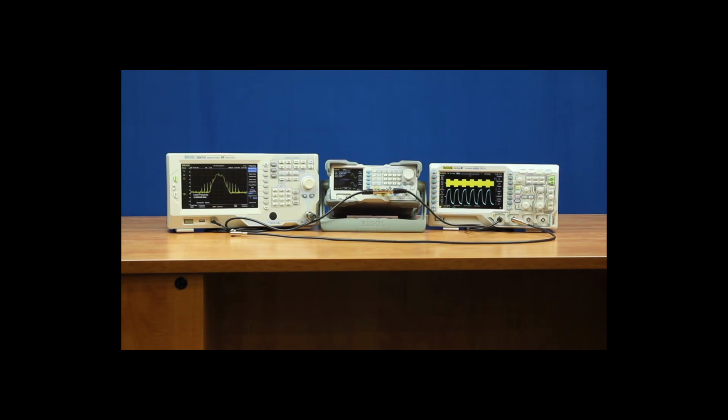So in the last example, we were transmitting and demodulating analog data. Here, let's look at a similar modulation, but with digital data. So this is an amplitude shift key, which is in essence an amplitude modulation where there are only two values, a high amplitude and a low amplitude, that are equivalent to a 0 and a 1. And now we've taken a slightly different connection scheme, and we've hooked up the demodulation audio port coming out of the DSA 710 and have it going into channel 2 on the scope, so we can see the bit pattern, in essence the ones and the zeros.